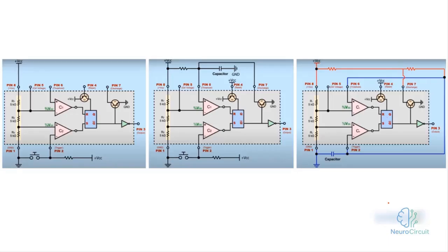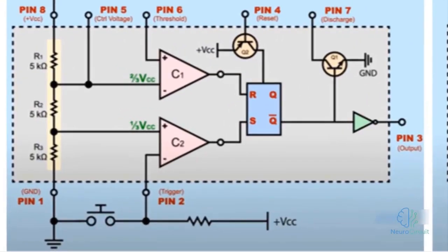Now, if I want to briefly review these 3 modes so you can have a clearer understanding, I can put it this way. If you just keep these 3 points in mind, you've already taken a big step forward. If you want to see how it works again, you can rewatch the video from the beginning. A 555 IC in bistable mode can be selectively triggered so that our output is either high or low, meaning it can be in either the upper state or the lower state. The inputs can also be activated manually or digitally for us using a button.